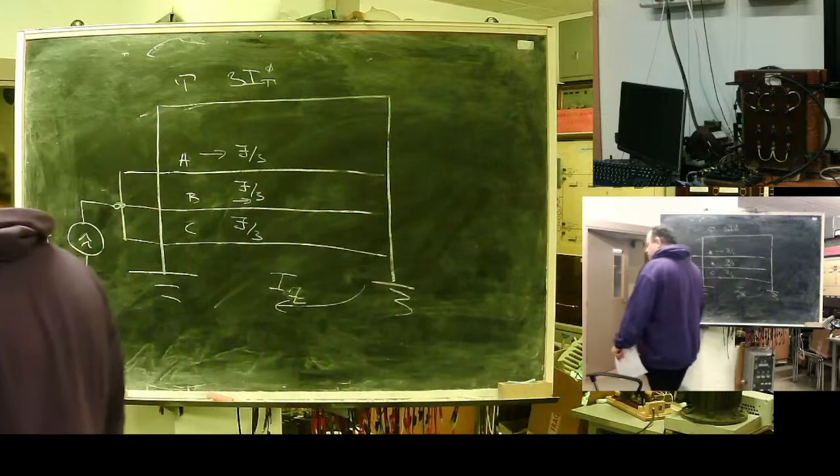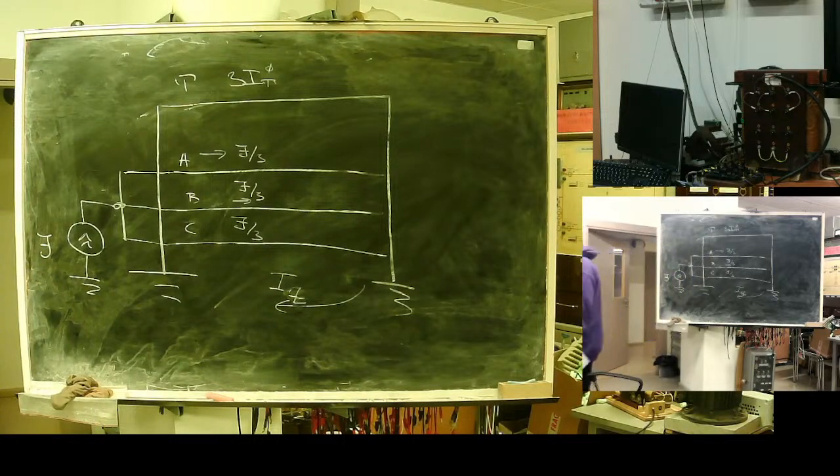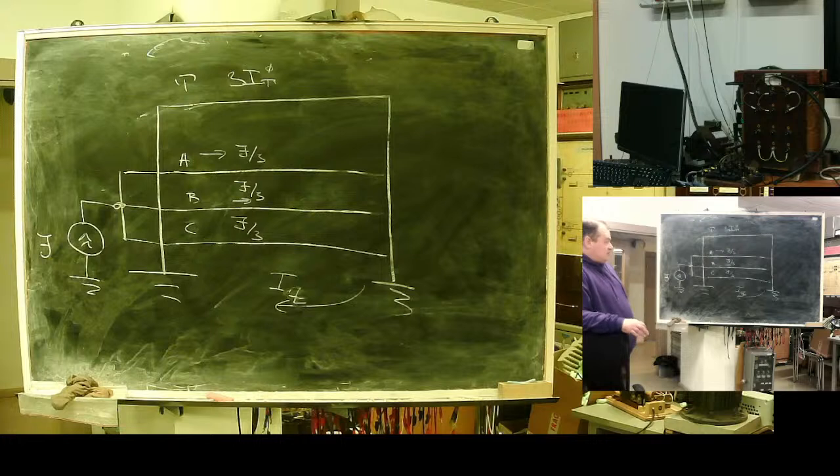If we are performing very precise modeling, what we need to do is model it in phase coordinates. Okay, it's possible, but in 99.99 cases, the influence for direct and negative sequence can be ignored. It's only accountable when we speak of very, very high precision.